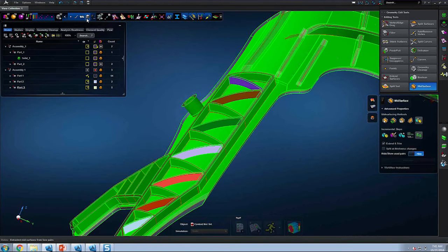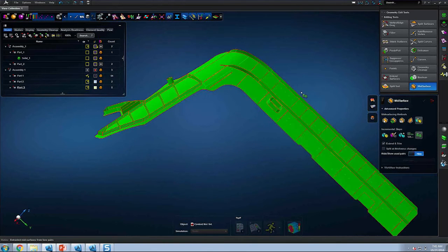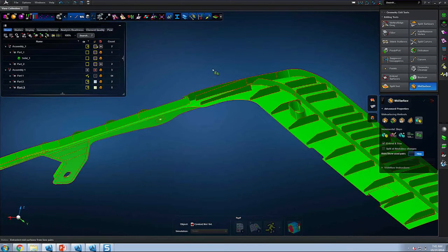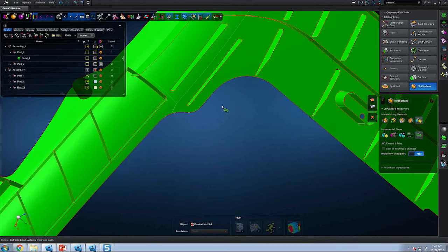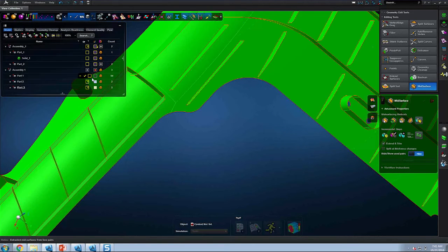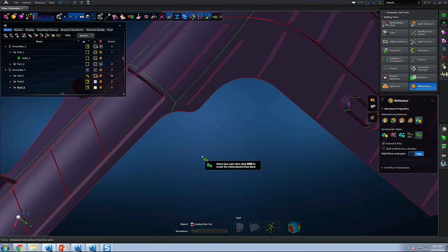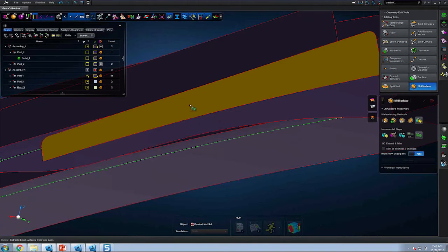Let me go ahead and hide that for a moment. So this is what the geometry finally looks like. I see that there is a mid-surface piece created for a majority of the ribs. Now I can fix some of these free edges, and let me change the color back to purple. This really helps communicate the fact that there are a lot of free edges here.